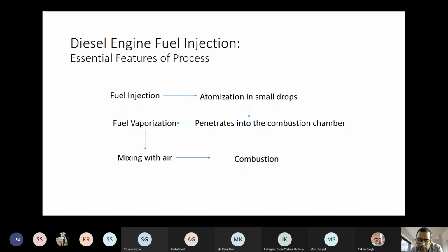Motoring pressure means there is no combustion, or the peak motoring pressure. Let us suppose the compression ratio is around 17.5. Take the gamma value around 1.3 or 1.35, PV^gamma equals constant, and take P1 as 1 atmospheric pressure. P2 will come to something around 40 to 45 bar.